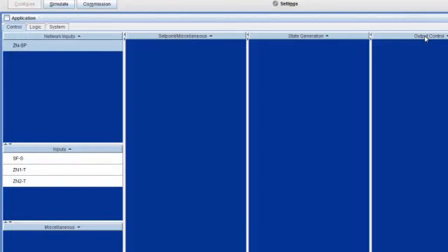I'm going to go ahead and do an average block. I need to average my zone temperatures together. And so I could just build an average function. Average functions are pretty easy. All I really need to do is add the two zone temperatures together and then divide them by 2. But there's also existing average modules. I could build a brand new module, add the average block to it, and build it that way. But here's what I do know. I know there's a module that already is built to do average.